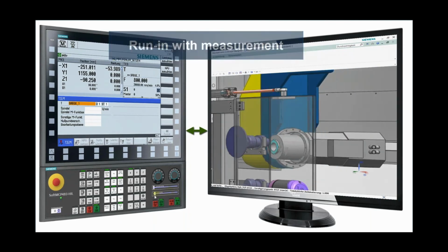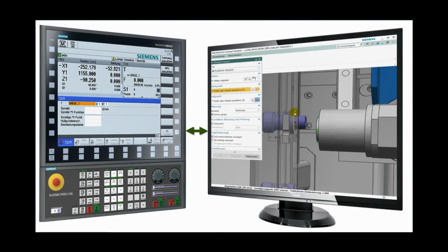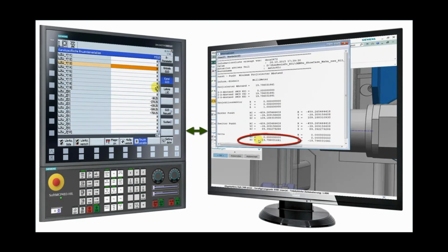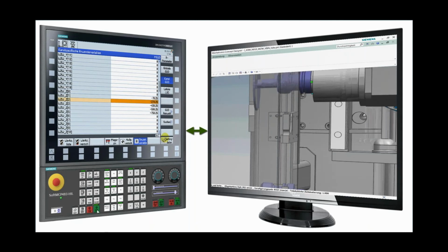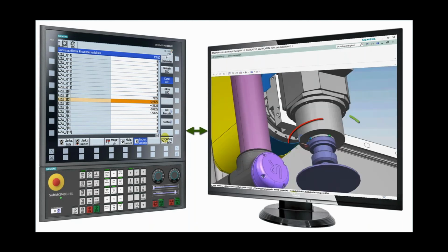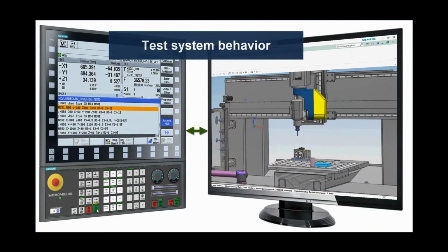And that's one of the keys. You'll notice in this that our tool, it's not lining up. And so we do a quick little measurement, and we can see that it's off by 19 millimeters, about 3/4 of an inch. With your eye, that could be difficult to see. And it could have been that the way you noticed it was by ruining something, but not with NX-MCD. We're able to do that test and check for everything. Or even just the system behavior.